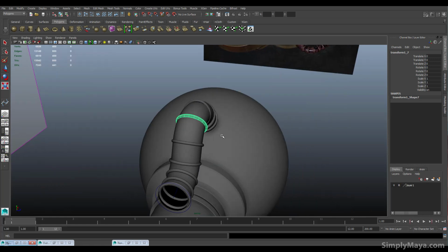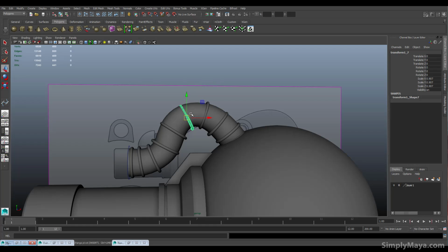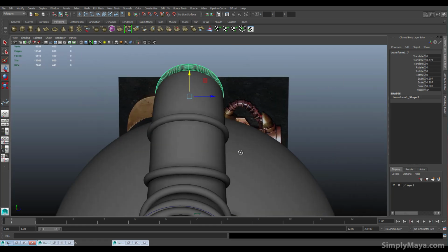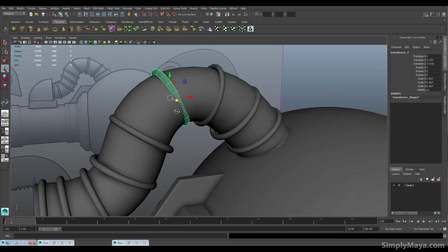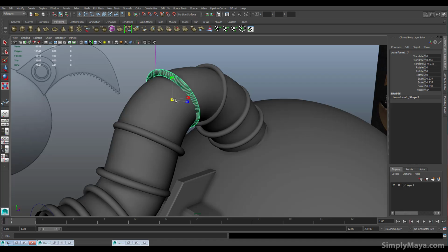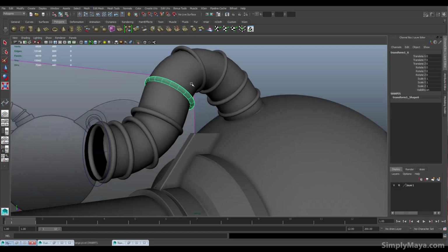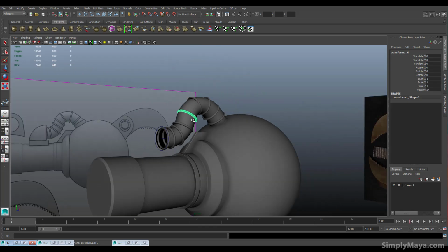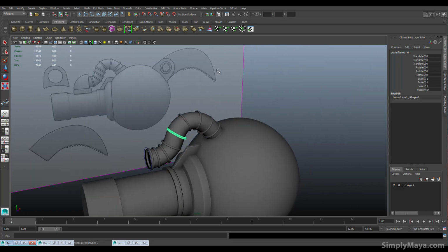Quite simple if you use a curve. And all you have to remember for this is to get the geometry out, we extruded along the curve, and then to get these multiple rings, we just used a motion path to attach a piece of geometry to, and then from that motion path we created an animation snapshot, which will work in pretty much any circumstance when you need to do something like this. So I'm going to be back in the next part and we'll look at creating the rest of this back piece and possibly starting on the main claw.